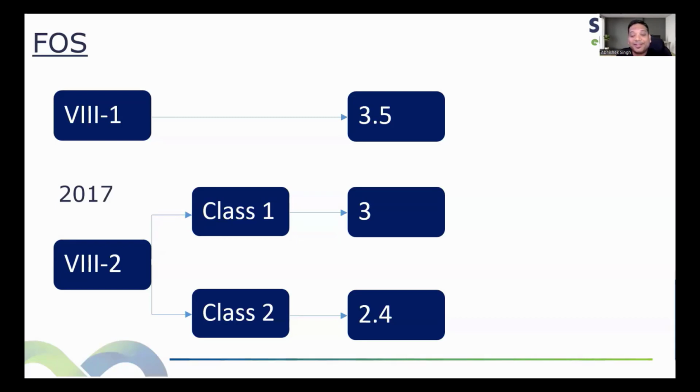U2G: when there are no rules available, or if fatigue is there, or creep is there, or if the design is such that there are no rules which we can fit in, then we do FEA. Same case is there with Division 2 Class 1 also.